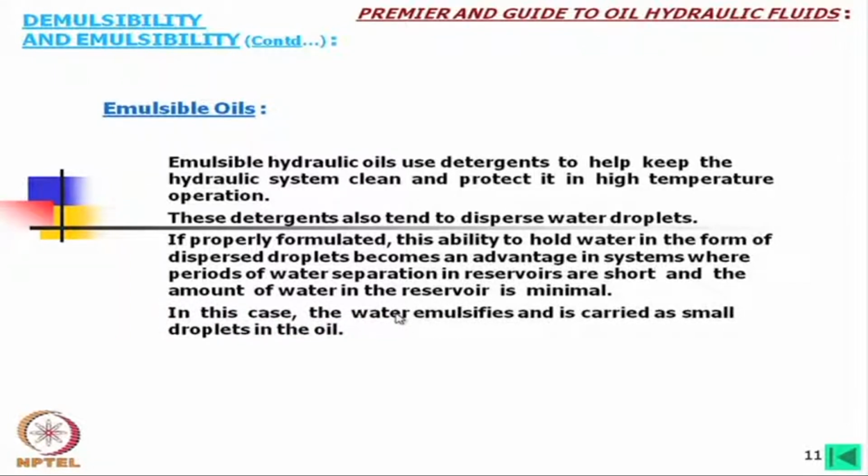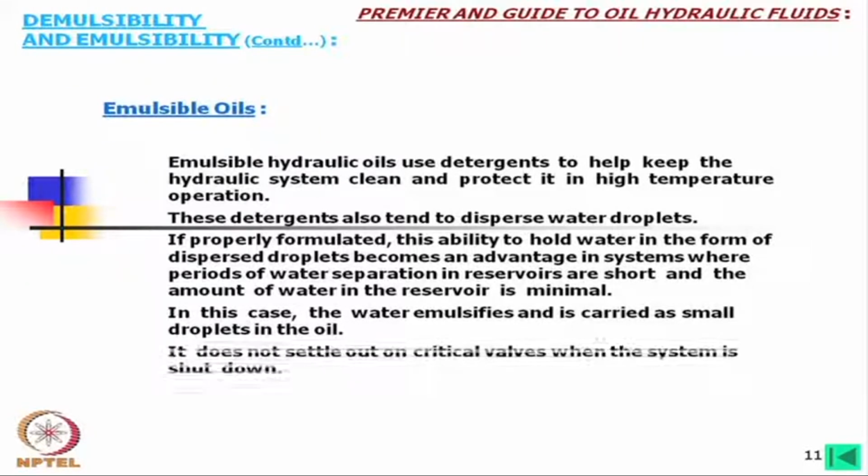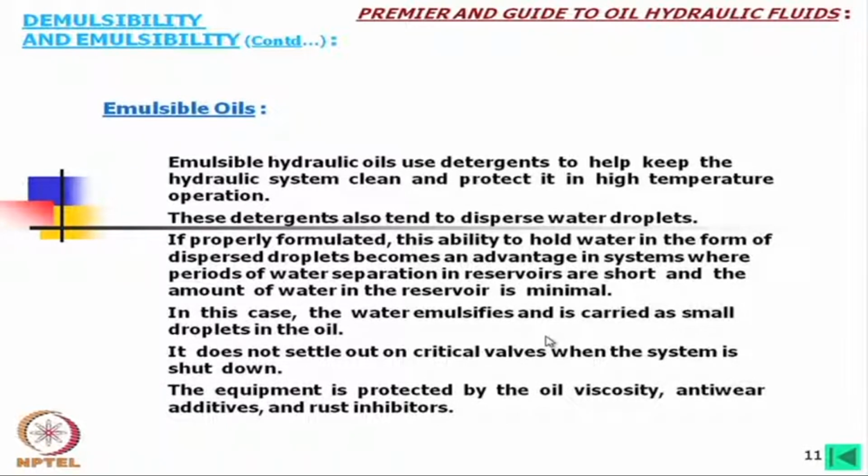In this case, the water emulsifies and it is carried as small droplets in the oil. It does not settle out on critical valves when the system is shut down. The equipment is protected by the oil viscosity, anti-wear additives and rust inhibitors.